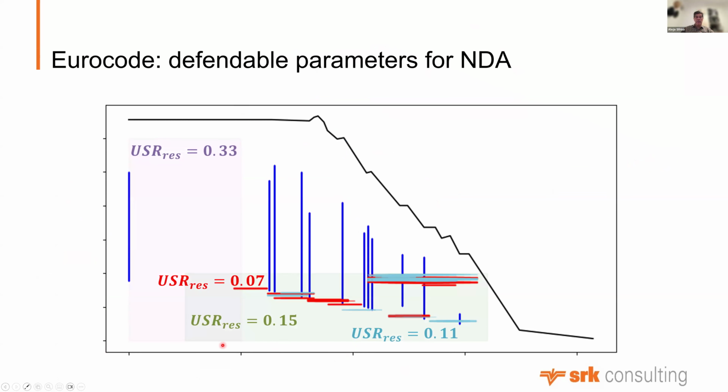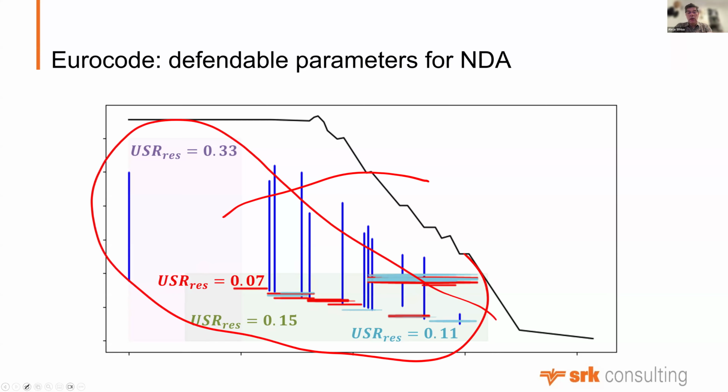So here is the box curve, and for average, you have this strength ratio for residual strength, which is high. And you have here the base, not within the weak layers, but out of them, you have a value of maybe 0.15 in this particular case. It's a real example. And you have two sets of weak layers. You are very unlucky if you go through this, 0.07, not so unlucky if you go through the light blue ones. All this is totally different and way more interesting than just picking one value for the whole dam.